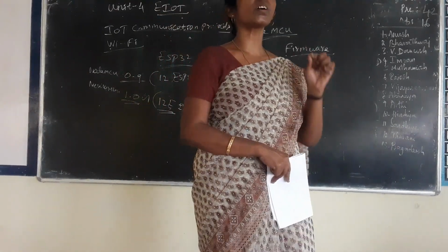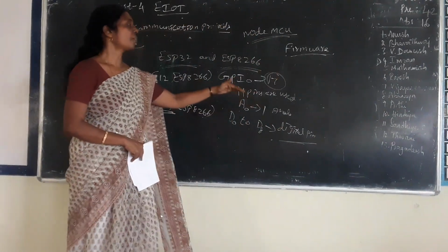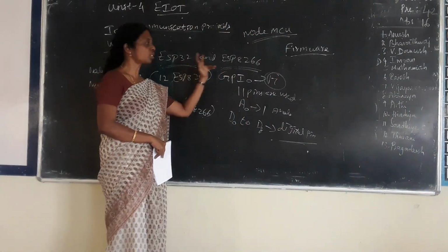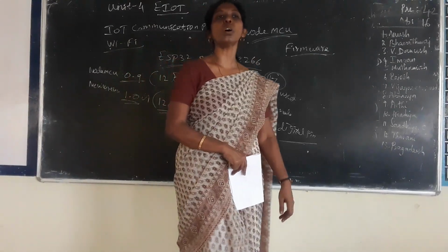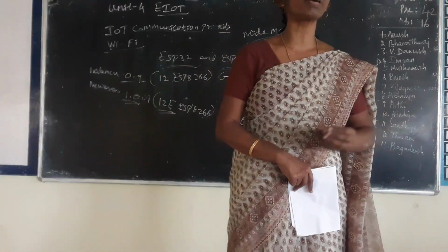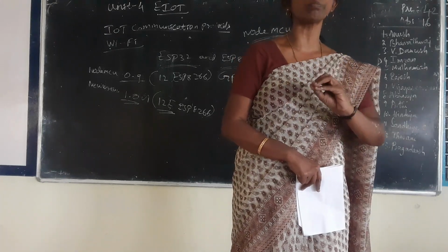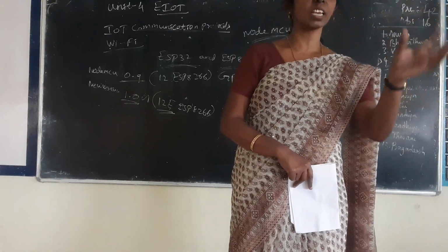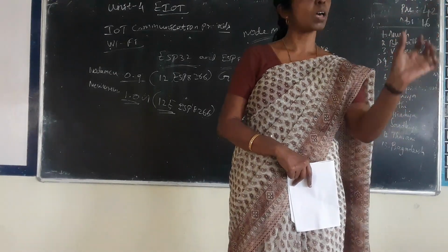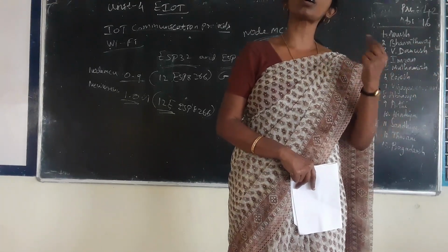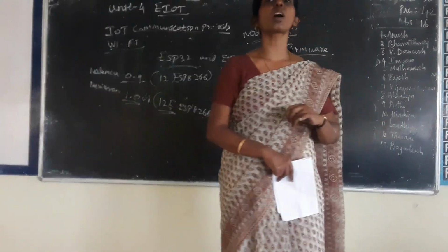Whenever you are using a Wi-Fi module, you have to remember which series of NodeMCU it is. ESP32 is also there, and ESP8266. The series which we are using is ESP8266. It has analog pins, digital pins, ground connection, the operating voltage, and the benefits we get in NodeMCU. Once the program is stored, it stays there, and we have a reset button. Once the reset button is pressed, it just reloads the program, but the correct program we have stored will remain inside. Are you able to follow?